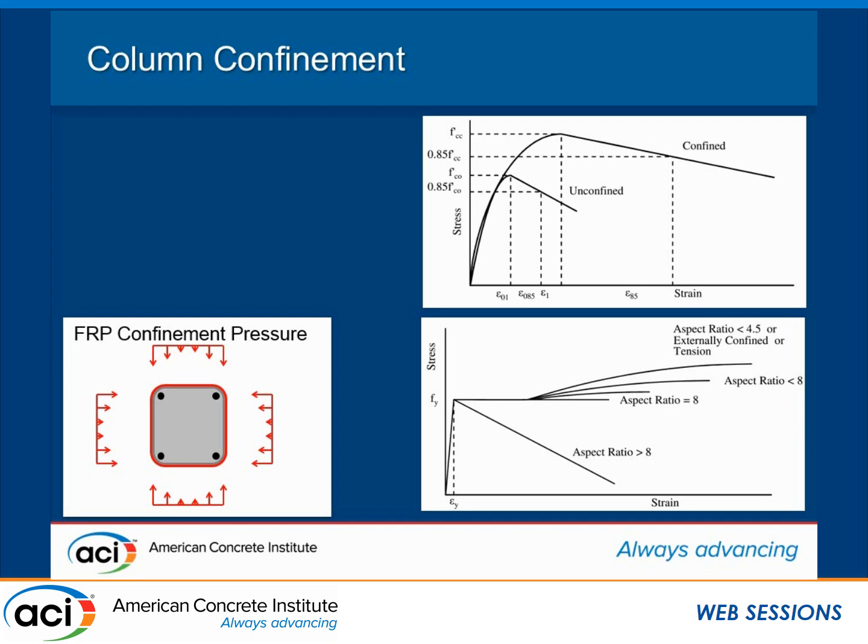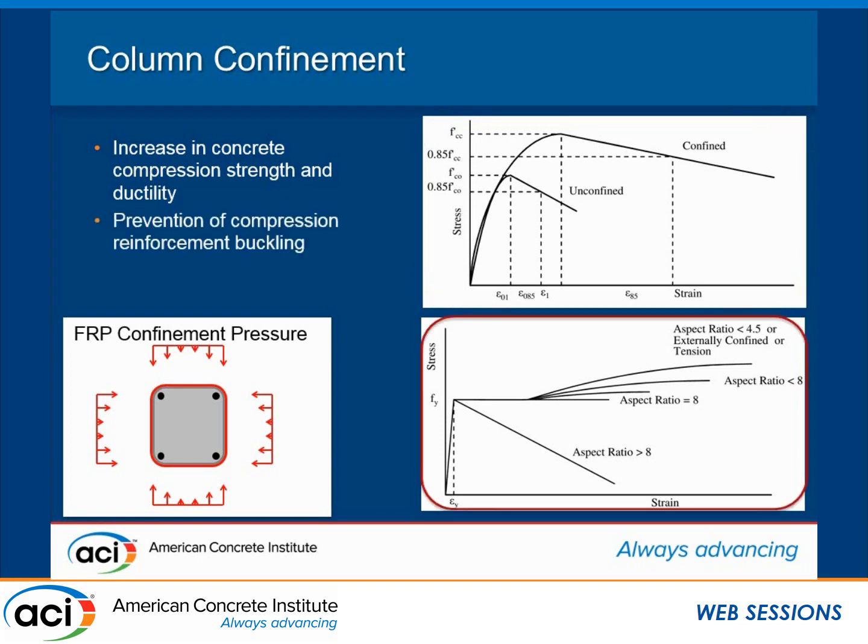And this has an effect on increasing the ultimate capacity of the concrete, f'c, and also increasing the material ductility. And the more you confine it, the better those benefits become. And as we can see, seismic confinement would act in here, whereas an FRP externally jacketed confinement would happen over the entire member. And also, if we prevent bar buckling, we can get beneficial compression steel.